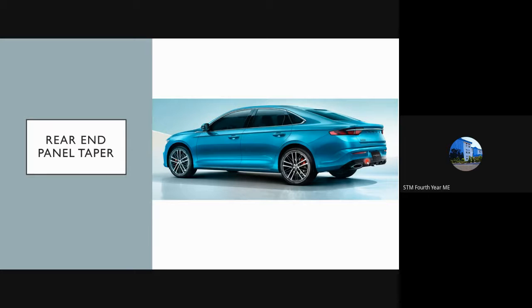The benefit of providing a taper here is to increase the negative lift. I have already told you the velocity of the air underneath the car will be very high, while at the front of the vehicle it will be low, and a high pressure region will be created here. But underneath the car there is always a high pressure region rather than above the car, and hence it will always provide a lift at the center of the car, while we have to provide a negative lift at this portion of the car also.